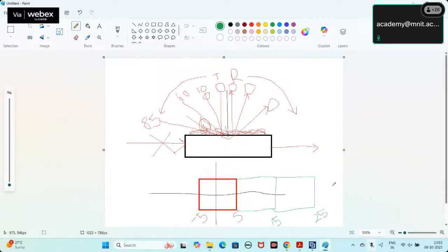If we make a Floquet port, then again this 3 cross 3 will turn into a 9 cross 9 or 27 cross 27. So directly we will make 3 cross 3 and apply a waveguide port, so that it can run that 3 cross 3 part only. That will not make any periodic structure anywhere. So at that time, this value is important.